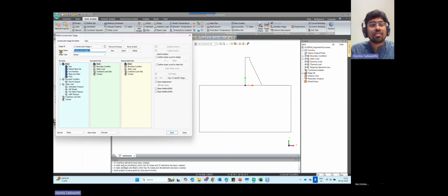So now let's go to the stage name, which is in situ. The stage name that we are considering is in situ. That means only rock will be present here. So right now on the right-hand side, which you are seeing is a simple geometry that has nothing to do with it. We need to make sure the mesh sets are activated. Okay. Let's give the stage name as in situ condition. In the initial condition, we only have rock, right? So let's activate the rock.